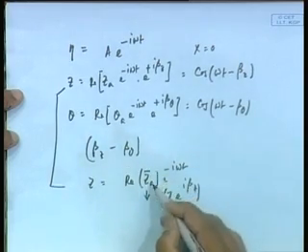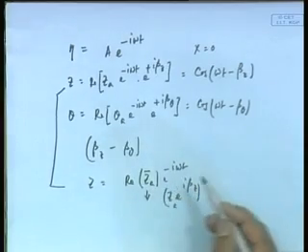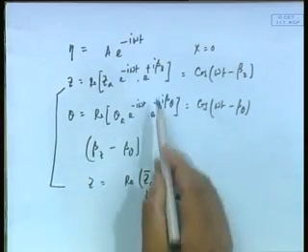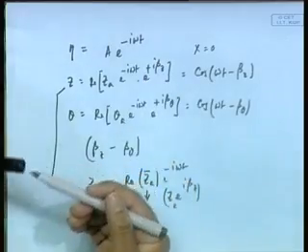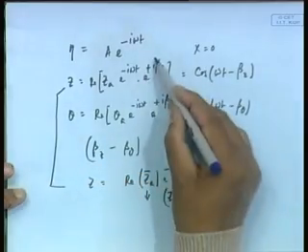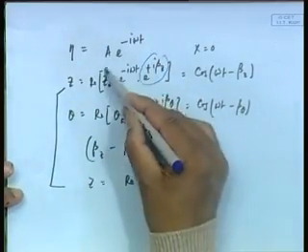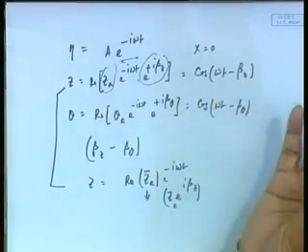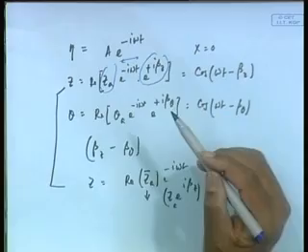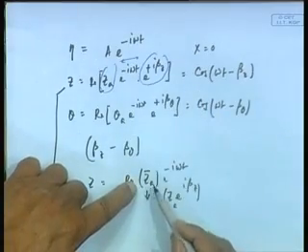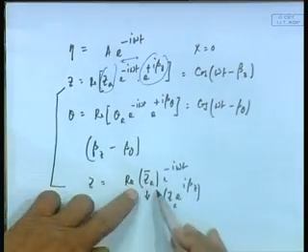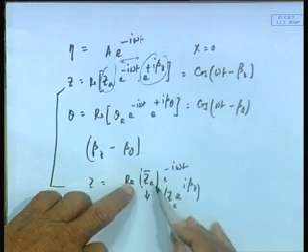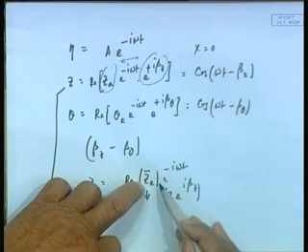This term is known as complex amplitude. It is a complex number, because if I combine this part and this part and call that z a bar, obviously that number is complex. So this signal is a sinusoidal signal in time with this amplitude, but this is the complex amplitude.